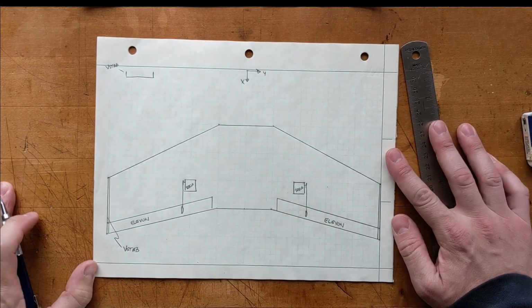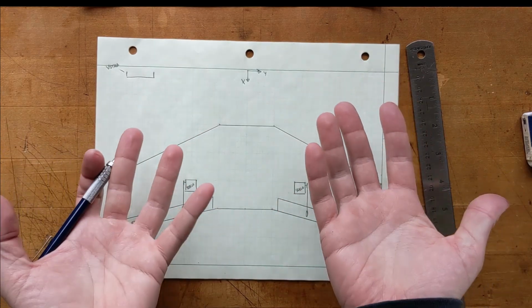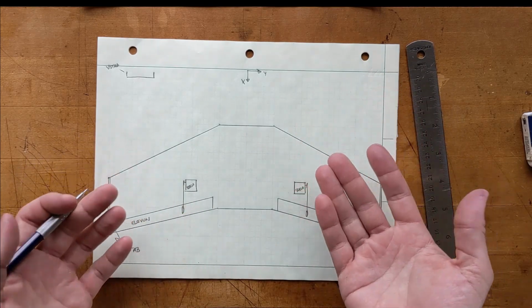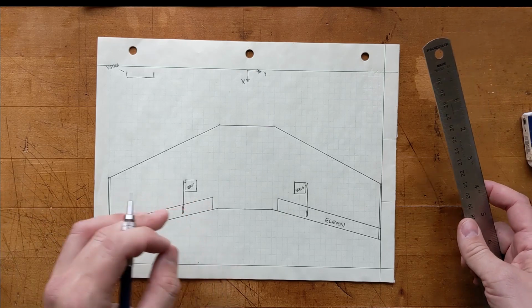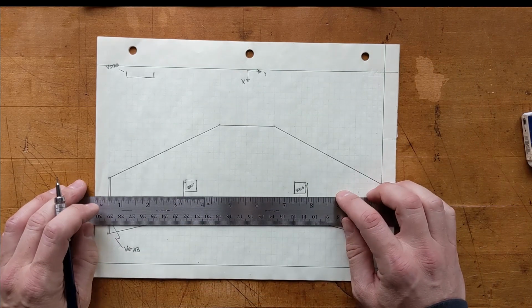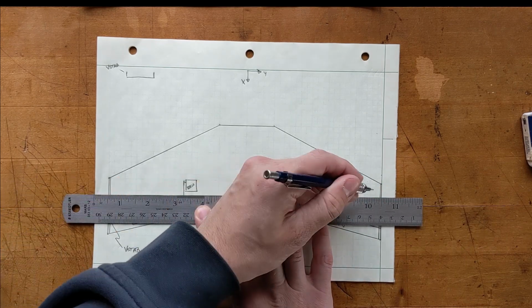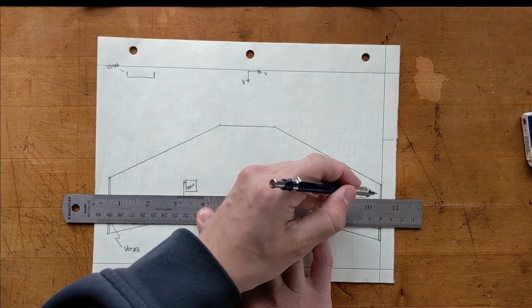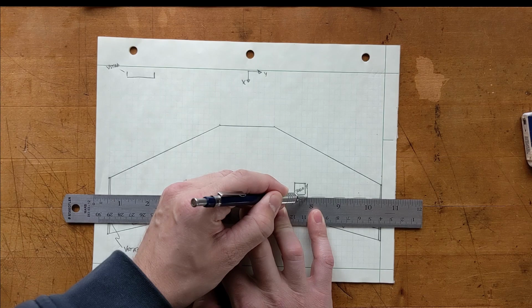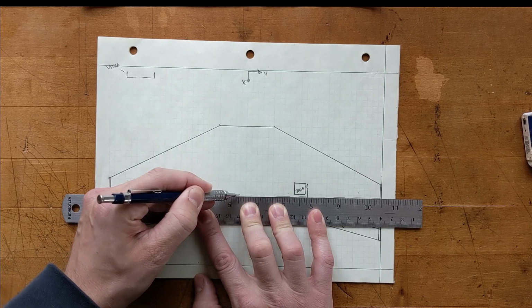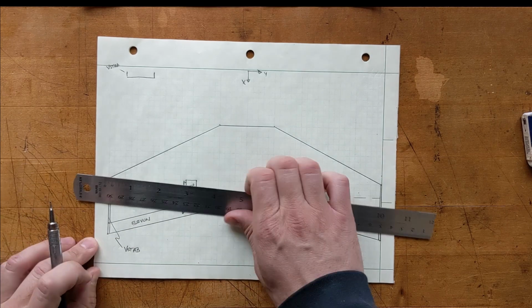Okay. Now, additionally, for some more strength, since this is going to have all the wing bending moment caused by lift on the wings, we might need some more strength, and a way to carry that through is by adding a spar. So let's just say we'll put it somewhere like this, and this is going to be kind of embedded in the wing itself. So I'll draw it dashed. And that'll be something strong, like a little carbon fiber tube maybe.